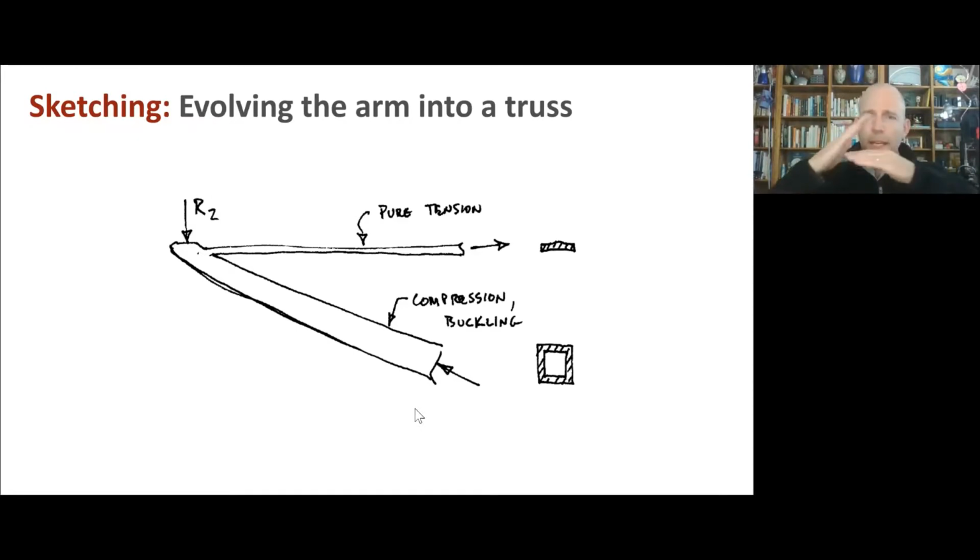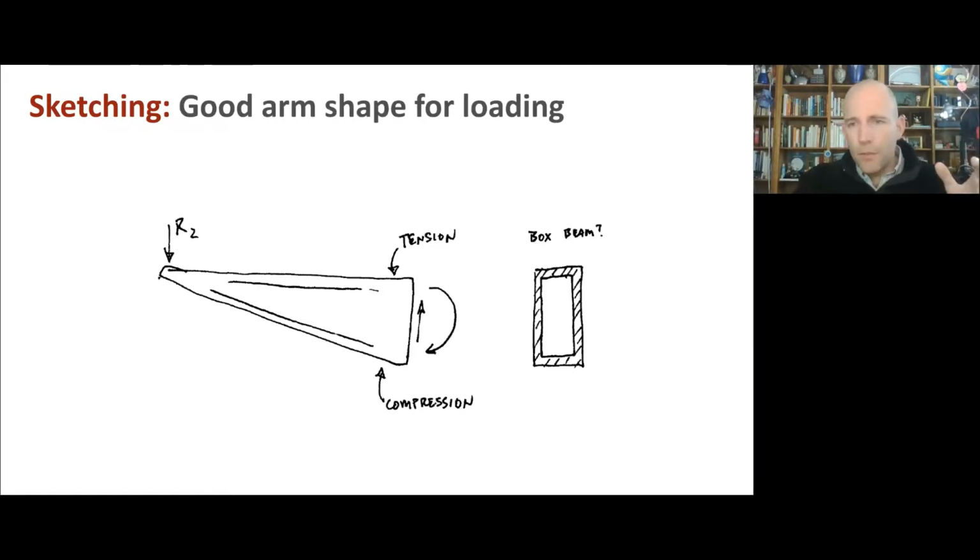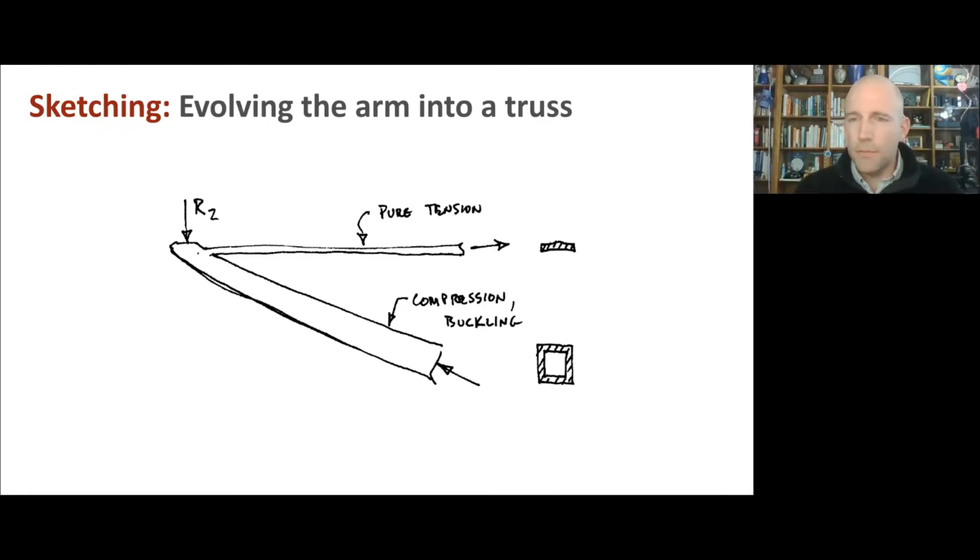Now, of course, if we make it too steep, then it'll have to go very far away, and that gets longer and longer. That hurts us for buckling, and it hurts us for mass. So some moderate angle is going to probably turn out to be best. It's hard to do that when we have this solid cross section, because as we make this side taller, these faces get longer and longer, and they add more and more mass to our part. So separating them out can be useful.